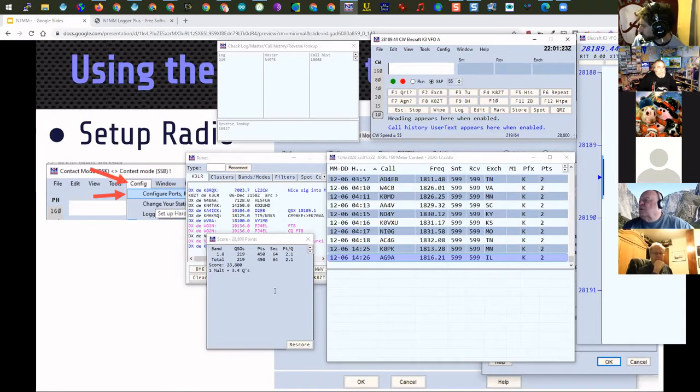Some radios like the ICOM 7300 let you do CW keying with the same USB cable used for control. Other radios don't let you do the same thing. So it depends on the particular radio. On the 891, with the one USB cable, you'll be able to do all of the control and frequency reading, but you won't be able to do the CW keying from it. Okay, thank you.